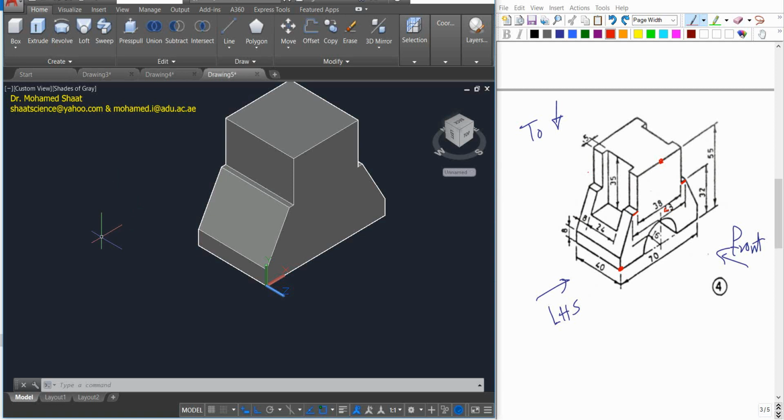Then this 3D solid will be subtracted from the entire solid. And this is what we're gonna do. So I'm just gonna pick circle, because for this hole to be created, you can draw a complete circle. It is not necessary to be typically the same shape. If you draw a complete circle and you extrude it, you're gonna end up with a complete cylindrical shape that will be subtracted. If it is subtracted from the shape, you're gonna end up with the hole, typically as it is already given to us here. Make sense?